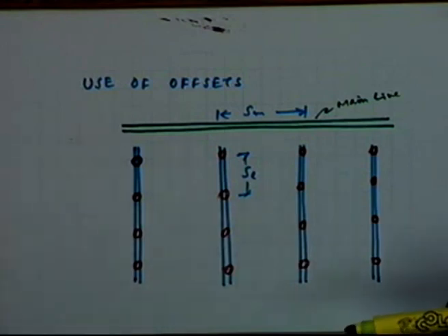But we have seen that invariably, if we look at the total field, a part of the field will be over irrigated, a part of the field will be under irrigated, depending on how much is the total depth of water you have applied. So if you want to keep the losses minimum, you might do so by sacrificing the requirement that all the field should be getting the minimum required, or the net depth.